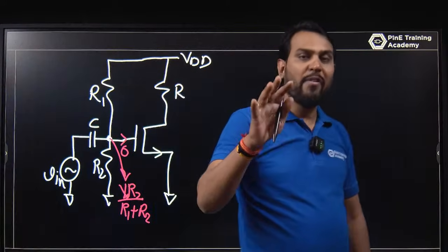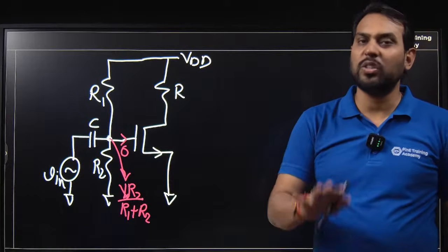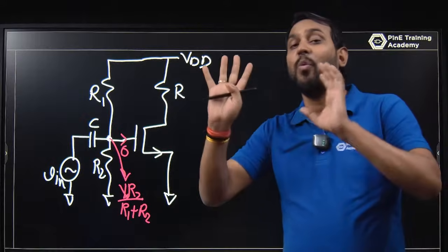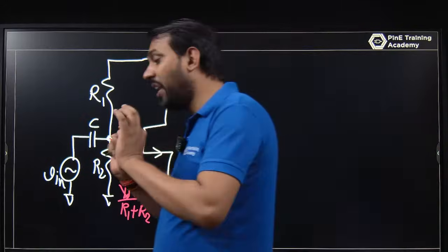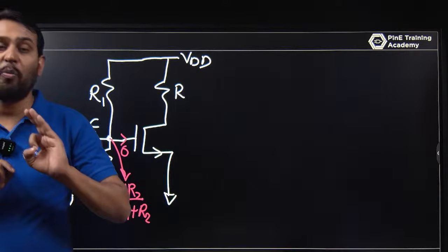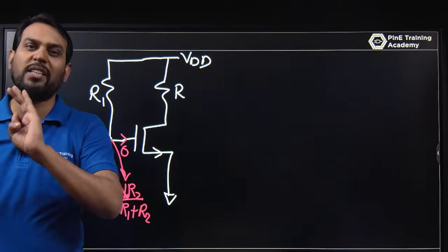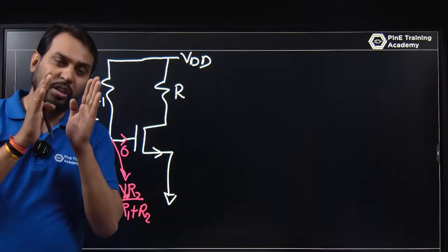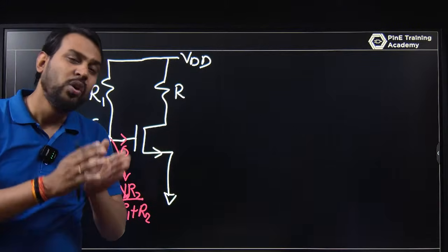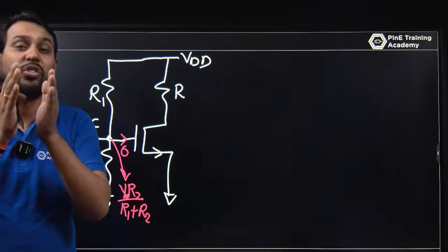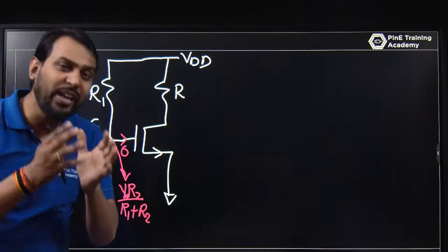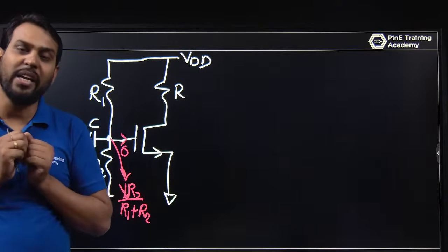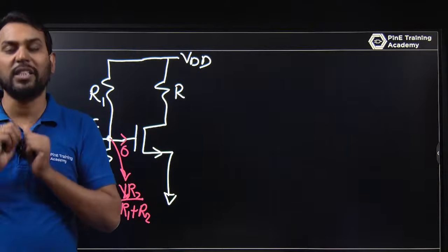Whenever you have a capacitor and a DC voltage, always treat it as an open circuit. It acts like an open circuit, it is not perfectly open. The word is very clear. Why? Because the current and voltage relation of a capacitor is I equals C dV by dt, and if the supply is constant, the capacitor has a constant voltage. So the current is zero, which means the capacitor acts like an open circuit, and it will observe maximum voltage across it.